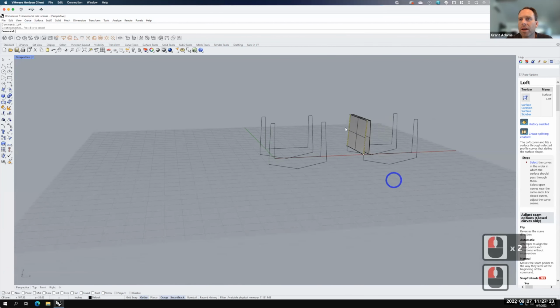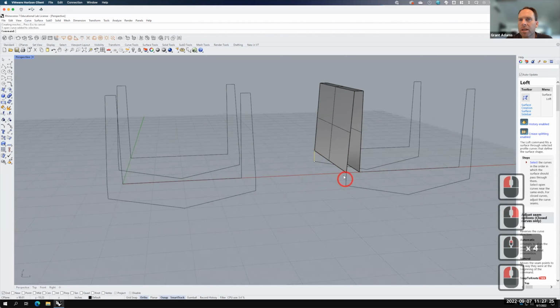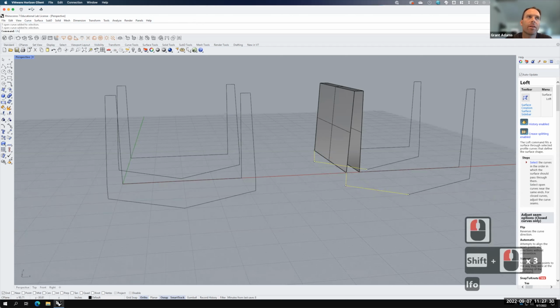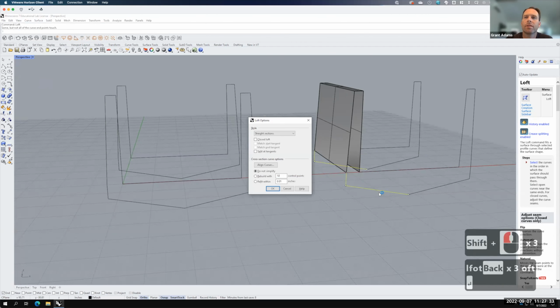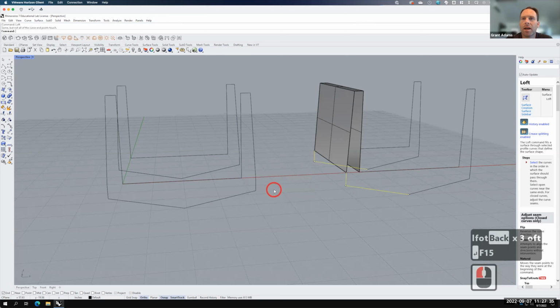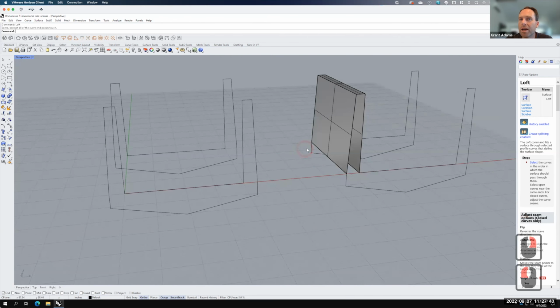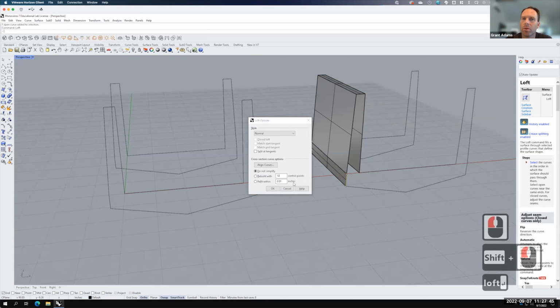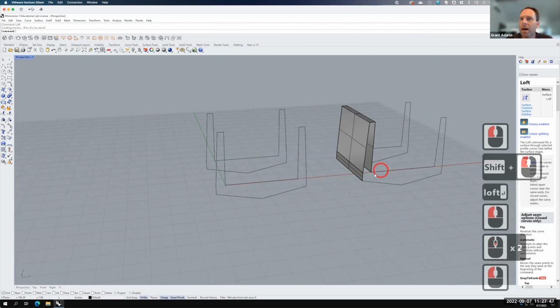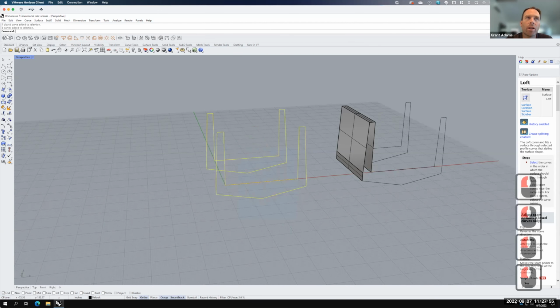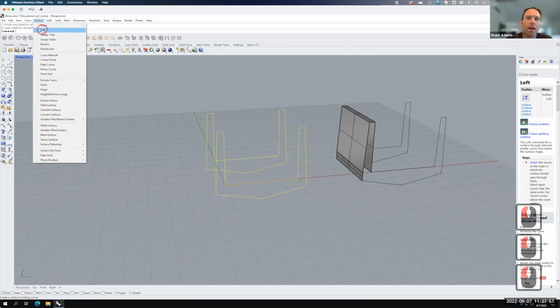Now, it should be pointed out that if I have individual line segments and I were to take, for example, those two and these two and try to loft them all together, I might not get the right results. In fact, I didn't get any results. So when they're not joined together, I have to just select two opposing curves and then loft those two opposing curves. If I keep these joined together like they are right here, when I perform the loft, I can actually do them all at once. So I'll select them both, go to Surface, and then Loft.